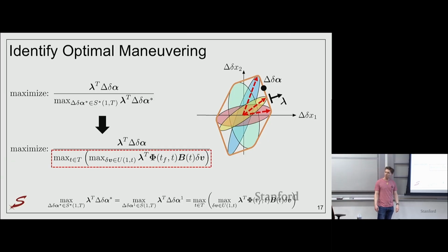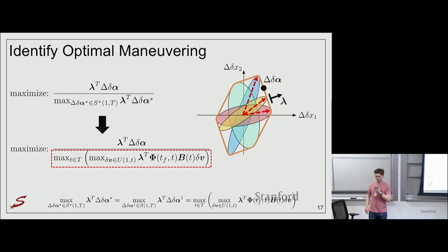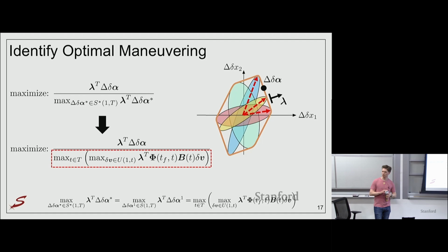So we have a few different reachable sets based on the different time step we're at within some control window, right? How do we know that if we take some control action at time step 1, the reachable set at time step 4 doesn't change because of it? Part of that is because you're dealing in pseudostate space. It's a linear system, so there are no nonlinear interactions going on. You're simply subtracting an effect away, right?